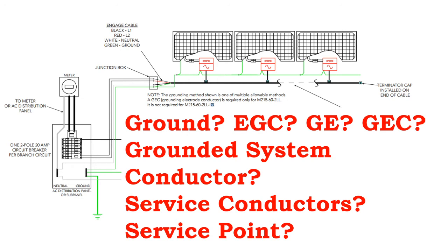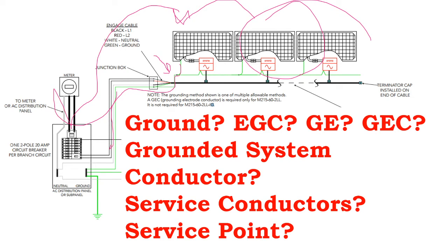And so a lot of electrical sizing is like, okay, what size does that ground need to be so that if this machine is faulting through that pathway, the breaker will open up before the current in that pathway starts catching so much heat that the metal it's ground faulting through catches the building on fire? So can we interrupt the circuit before that happens?